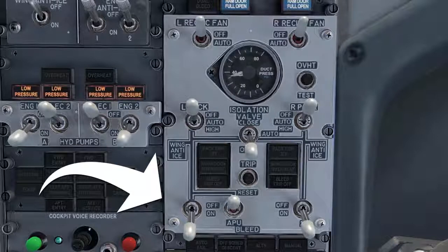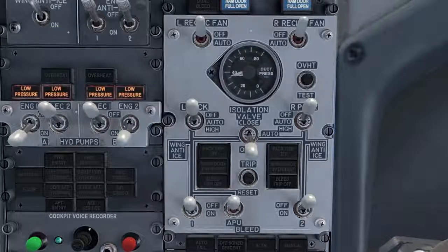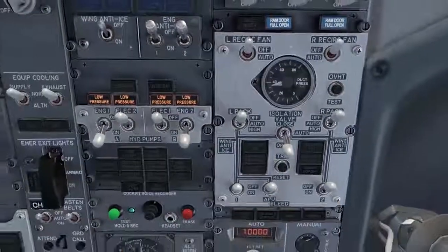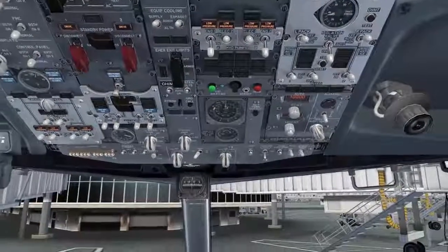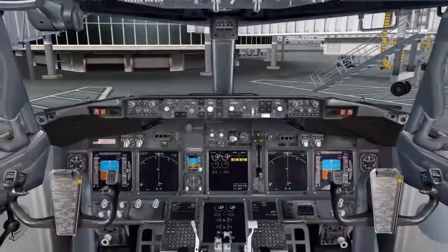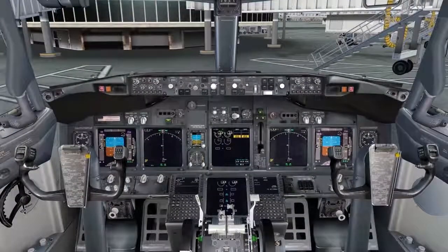On opens the related engine bleed air shutoff valve when engines are running, and off closes the related engine bleed air shutoff valve. Bleed air temperature is cooled in a cross-flow heat exchanger referred to as the pre-cooler. Ideal bleed air temperature should be between 199 degrees Celsius and 229 degrees Celsius, and it is achieved by exchanging heat between cool engine fan air and bleed air.